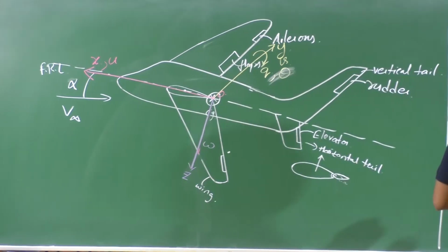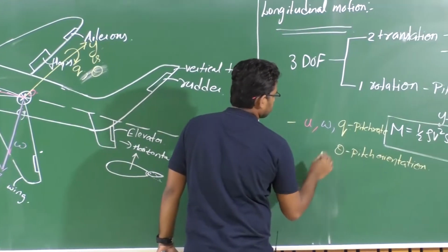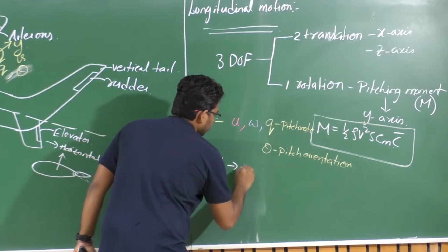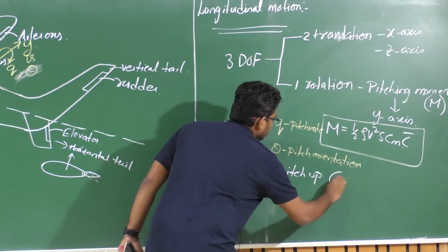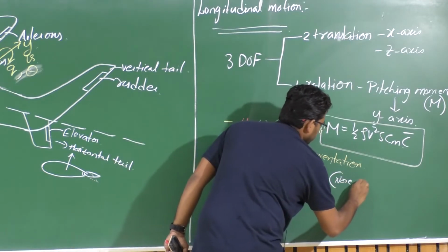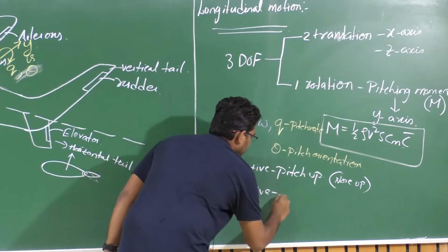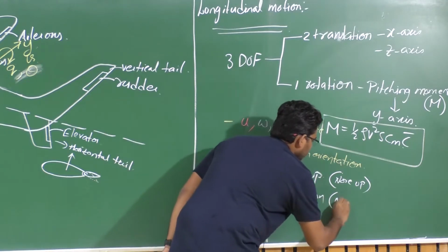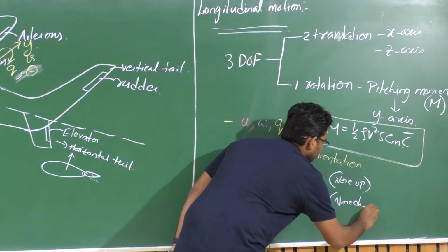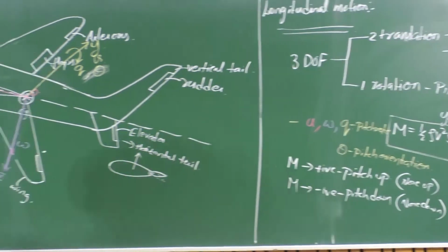So pitch up is positive. The moment is positive when it is pitch up, which is nose up, and this moment is negative if it is pitch down or nose down. Okay. So similarly, we have lateral directional motion.